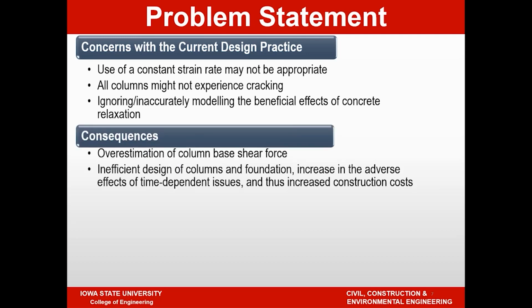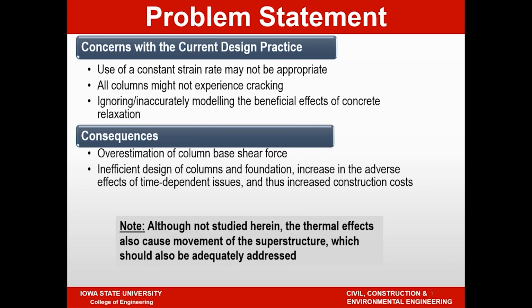If you don't account for the relaxation, obviously you're going to overestimate the column shear forces. Overestimating the column shear forces will lead to inefficient design of columns as well as the foundation, increasing the adverse effects of the time-dependent issues, because if you overestimate the forces, you increase the stiffness, therefore the forces in the columns and foundation are going to increase, and ultimately all of this is going to increase the cost of the structure. And then I already mentioned that thermal effects are a possible cause of introducing additional deformation of the superstructure, which should be accounted for